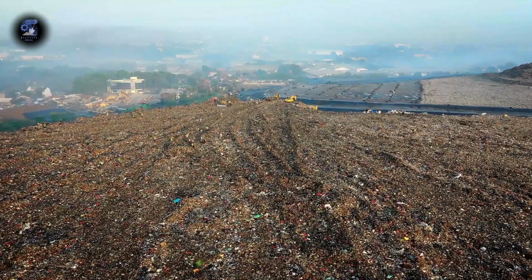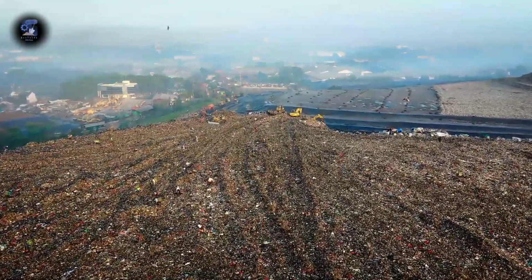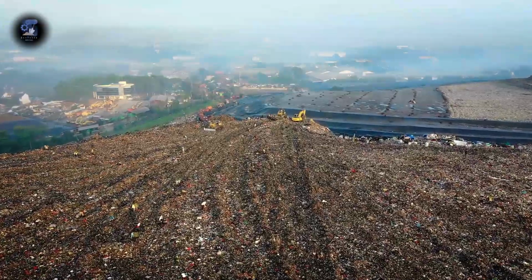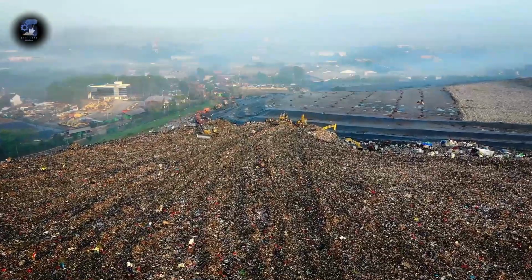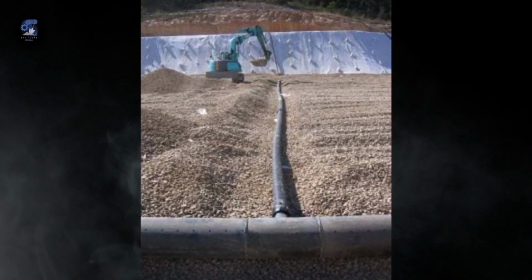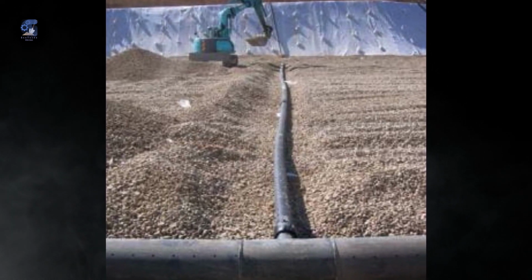To complete the leachate collection system in the primary liner, a network of perforated PVC pipes is sandwiched between a layer of gravel and sand. The sand and gravel act as a filter, separating large garbage materials while allowing leachate to pass. You see, some of the waste constituents are sharp objects such as disposed construction materials like glass, concrete, and rebar. Therefore, the layer is also a protective shield that cushions the geosynthetics and membranes in the liner system from damage.